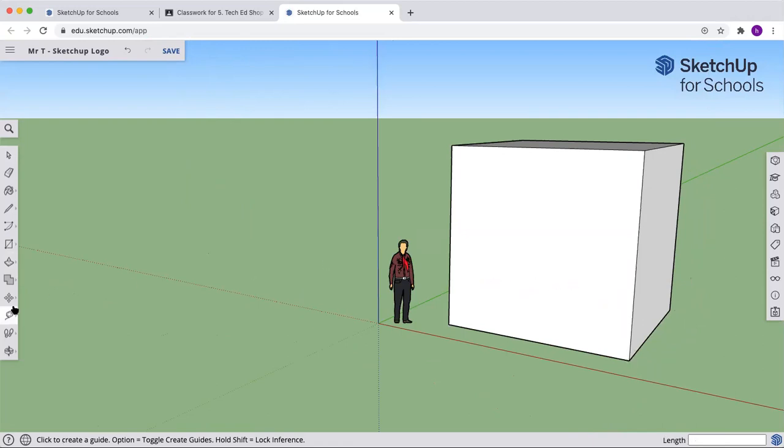There we go. Now, one of the skills that you'll need to know is to be able to scale things down. Let's scale this down right now. It's clustered in with the Move tool. I've selected everything. Pick the arrow, triple click to select your whole item, and everything there, we are going to scale down. Go on the Move.